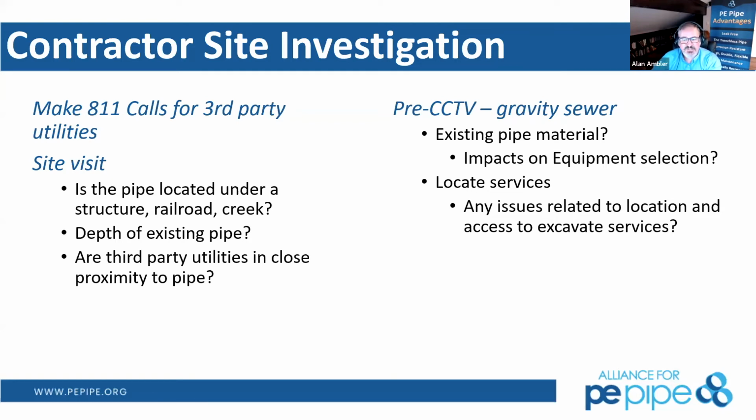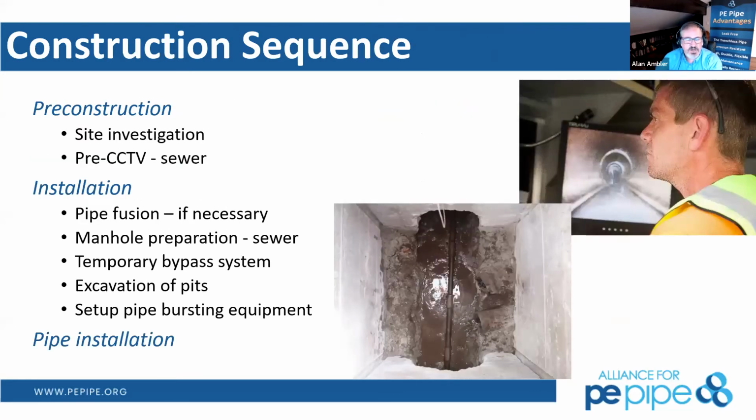So Diane asked us a great question about pipe bursting through multiple manholes and then reinstating channels as done in CIPP. Absolutely. The next slide for us here is going to talk about that construction sequence. When we're pipe bursting through multiple manholes, obviously the length of both runs is additive.